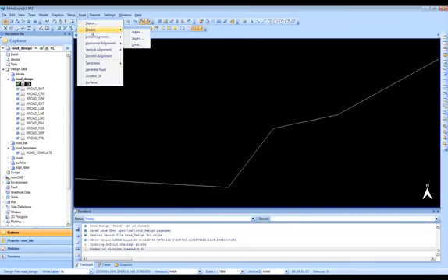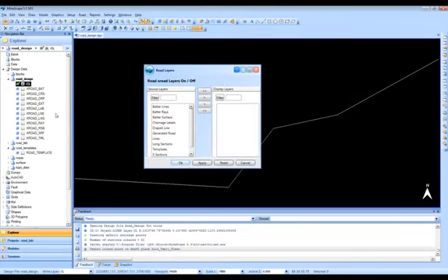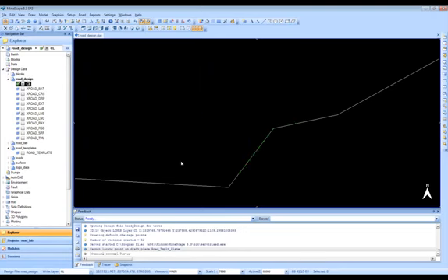The other thing you also have under the display area is you can choose what layers you want on and off. You can certainly turn them on and off here, but this particular one gives you some more meaningful names. So here I want the lines on, I want the batter surface, so that generated road. These are the different design elements that really relate to what these layers are, in perhaps more meaningful terminology. So there is my initial road, and we have the stations, the intervals that we've specified in our design.